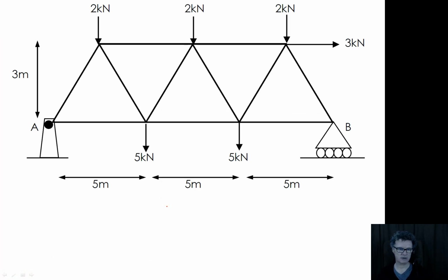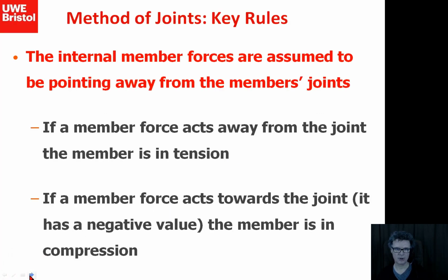So we've looked at this kind of framework problem. How can we go about applying a method of joints to something like that? So we're looking for the forces that are inside that framework, and we're going to define our forces as if by assumption, a bit like I've done with my string and my strut there, that those forces are always going to be pointing away from my supposedly contact point, my joint point, where I'm applying the external force. Okay, so they're pointing away from that.